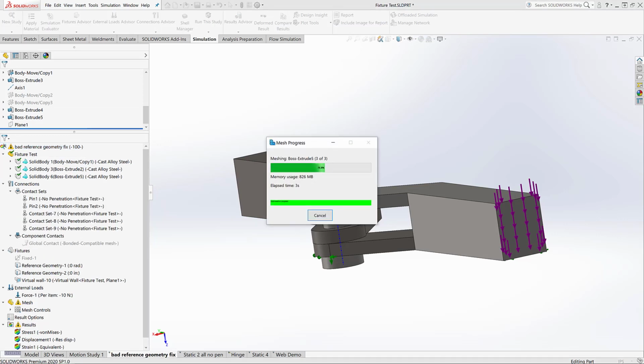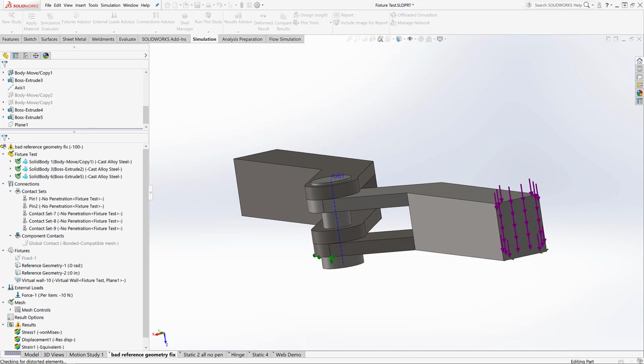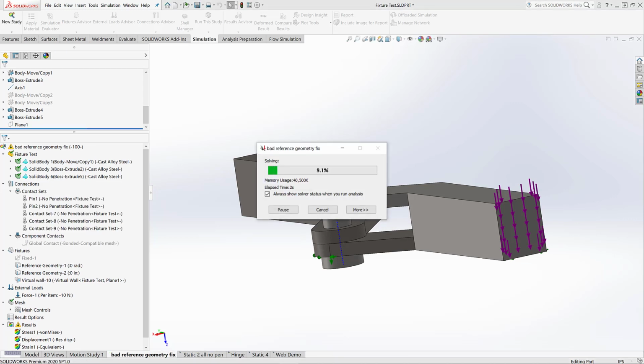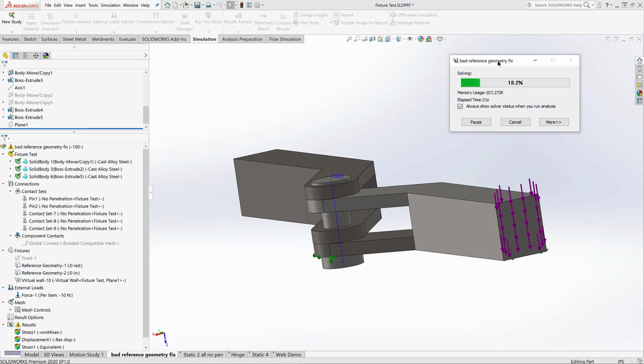No penetration contacts talked about. In the real world, it isn't safe to say that there is no penetration between two contact faces. True. Take, for instance, the bolt in the hole. Cylindrical face of the bolt simply rubbing against the surface of the hole. They never penetrate one another, do they? True. I mean, no, they don't, unless you have breaking or melting. But we have to keep in mind that we're telling SOLIDWORKS that these are not supposed to pass through each other. And that's going to keep them held at a certain type of rigidity for our example.